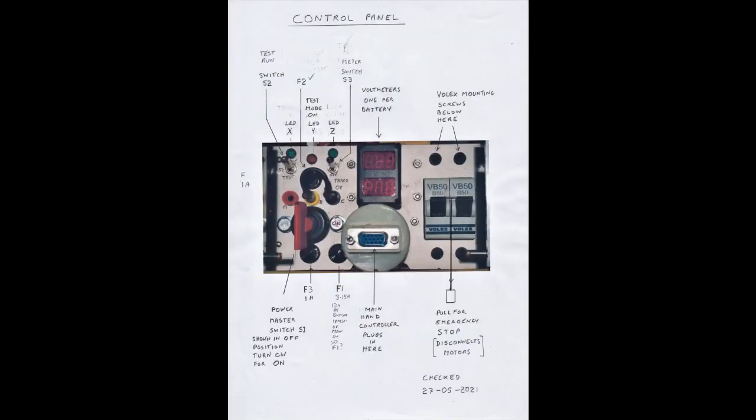This photo shows the control panel situated below the rear tender plate. There's a master isolating switch, the actuator of which can be removed for safety, and 3 fuses, plus a number of switches and LEDs that can be used for testing purposes. The motor wiring goes through circuit breakers, which could be operated at the back of the tender in an emergency.